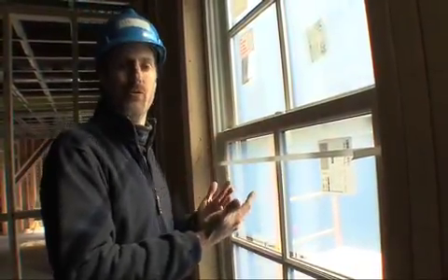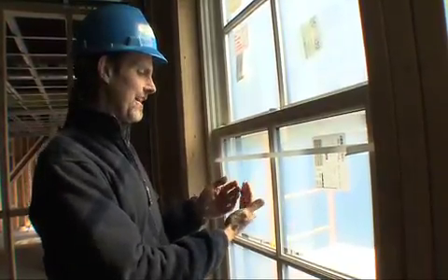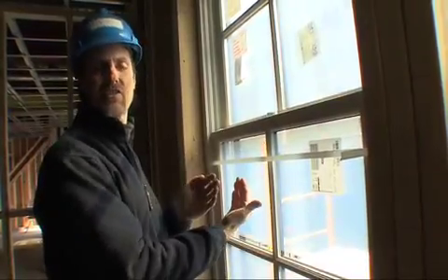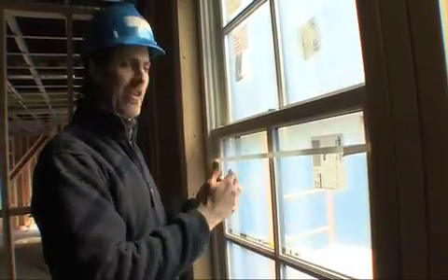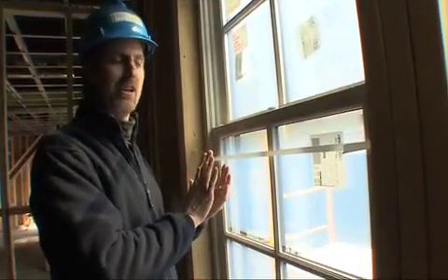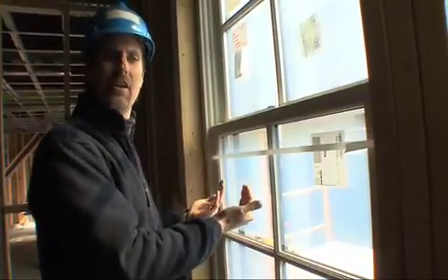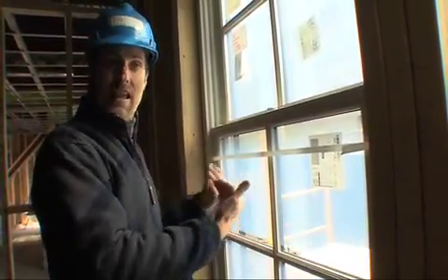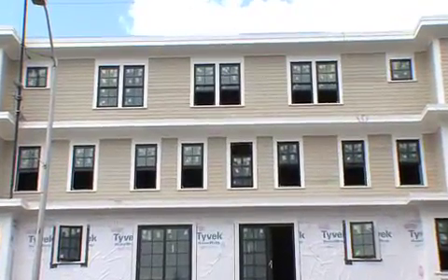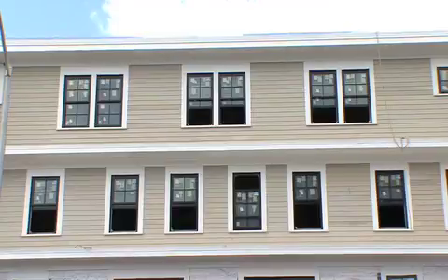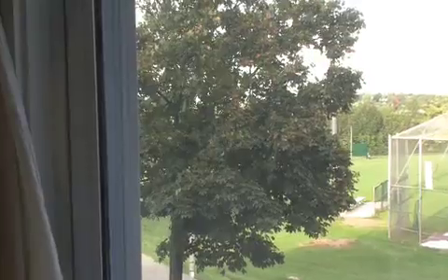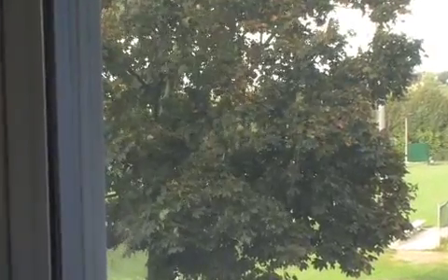You can actually look through the window and see outdoors, but that coating reduces the radiative coupling between the inner pane of glass and the outer pane of glass. And so that actually improves the thermal performance because you're cutting down on that radiative heat transfer. It also cuts down on the solar radiation entering into the building, which really helps on reducing the air conditioning loads in the summer. Daylight that comes through windows can offset the need for artificial lighting and also provides a psychologically healthy connection to the outdoors.